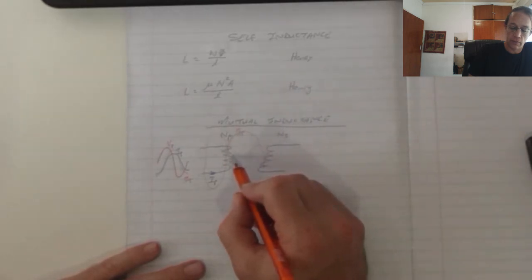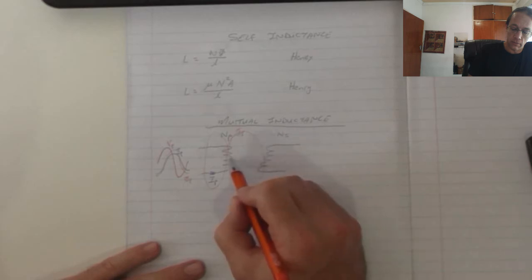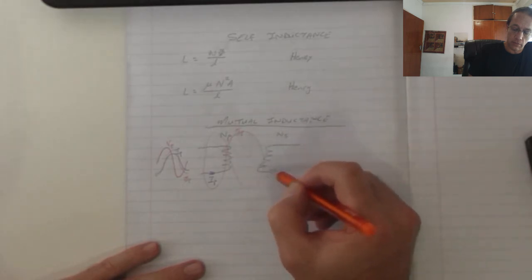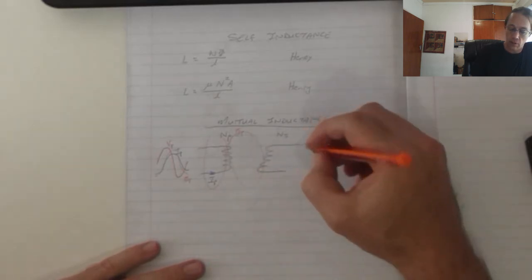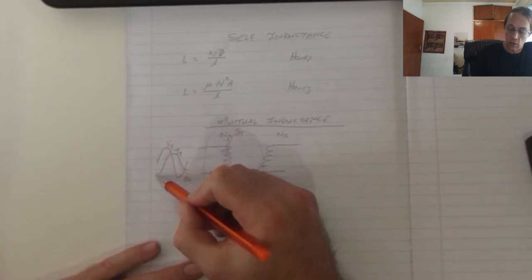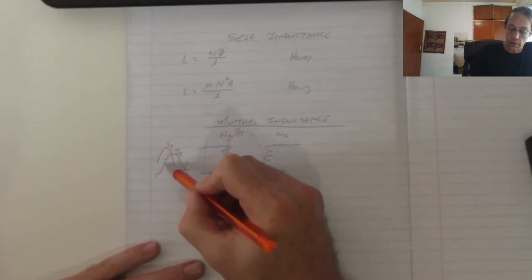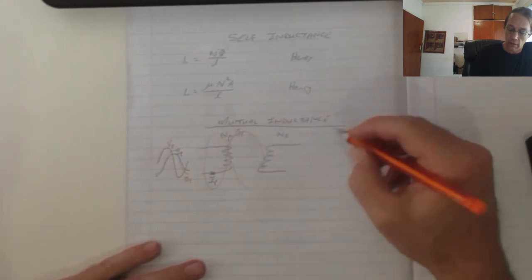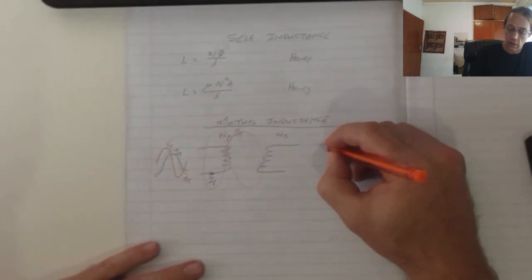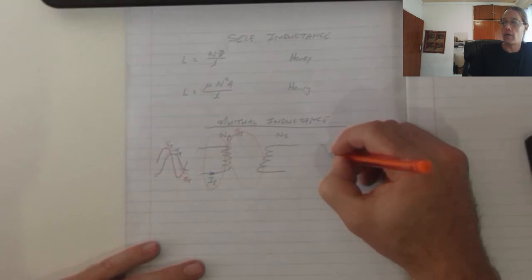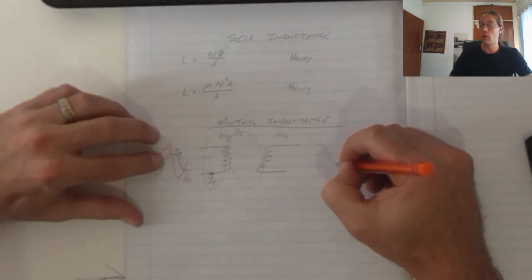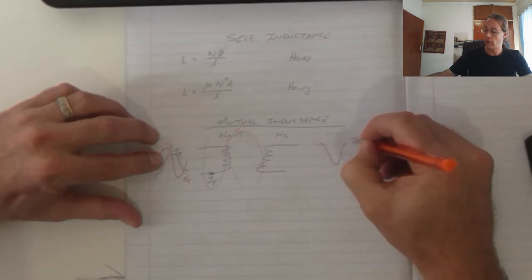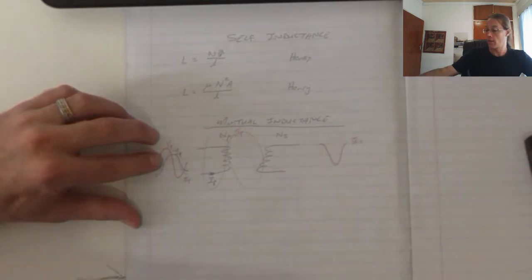Okay. Now, as this magnetic field increases and decreases in size, this second coil will experience this exact same magnetic field, but in the opposite direction. So as this decreases from negative maximum to 0, this side will experience that magnetic field as a maximum falling back to 0. And then as it goes on over here, it will go in the negative and then again into the positive, giving me a secondary magnetic field experienced like that.